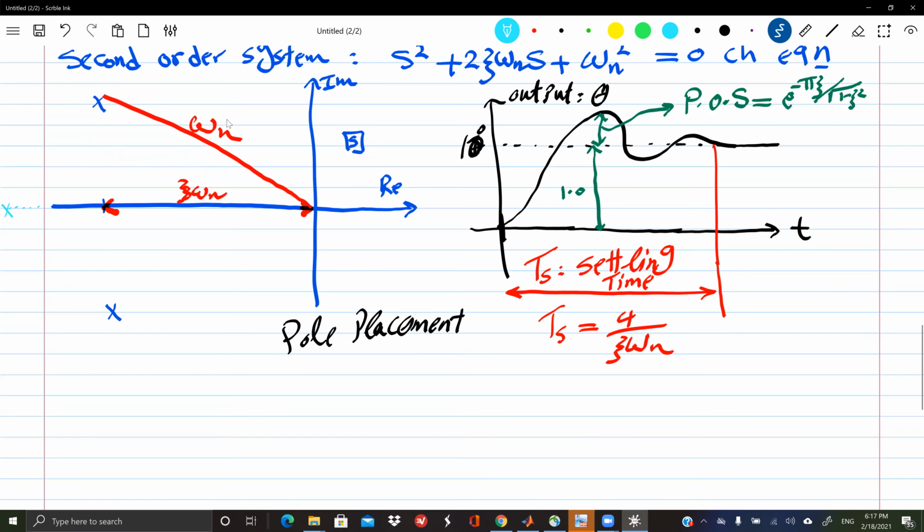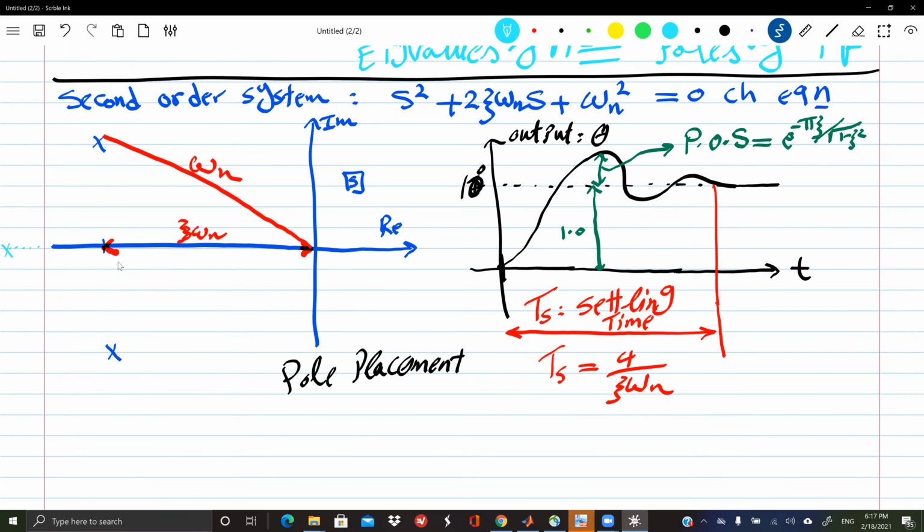Typically, we will have more than a second order system, right? But we typically care about what we call the dominant poles, the ones that are closer to the imaginary axis. Particularly if this one is really far away, like 5 times the real part, then it will really not affect the performance. We will care about the dominant ones. This is a very good point, so thanks for bringing it up. I'm coming to it in a minute, because it differentiates classical control theory from modern control theory.